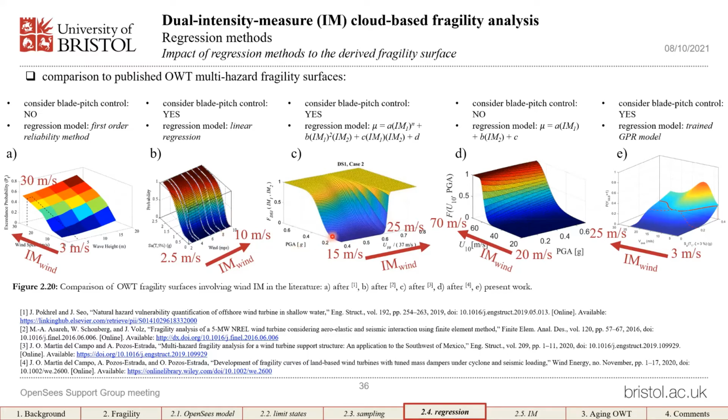For the third case this time, the wind speed was always higher than the rated wind speed of the turbine, so the structural demand was expected to be monotonically decreasing with an increase of wind speed. For this case, the use of a polynomial regression model is going to be fine, because neither overfitting nor underfitting will likely happen for monotonic data.